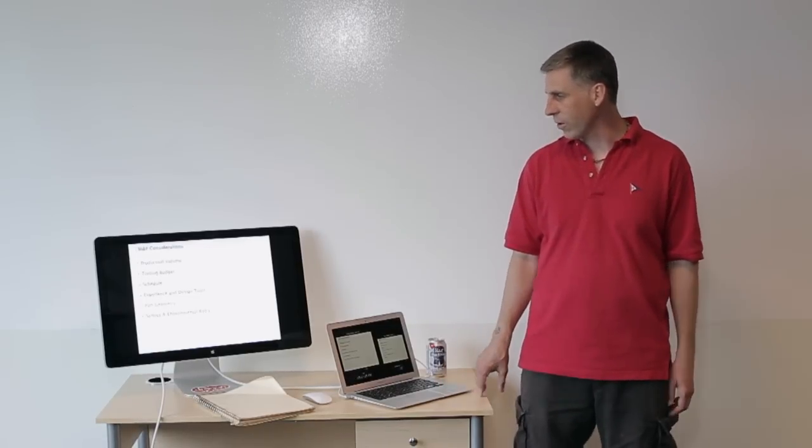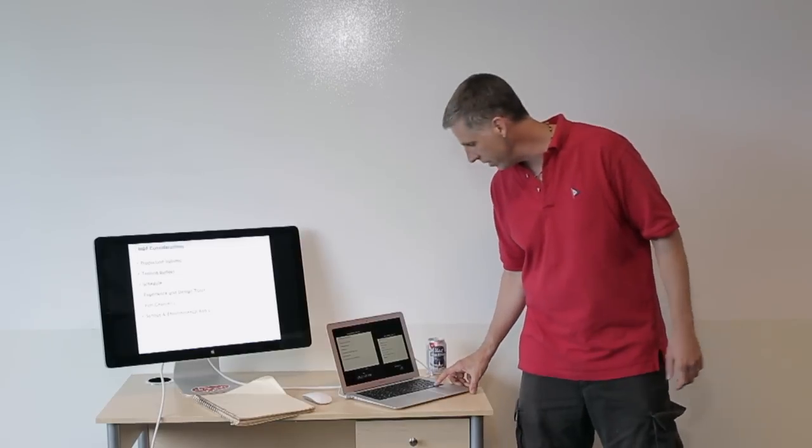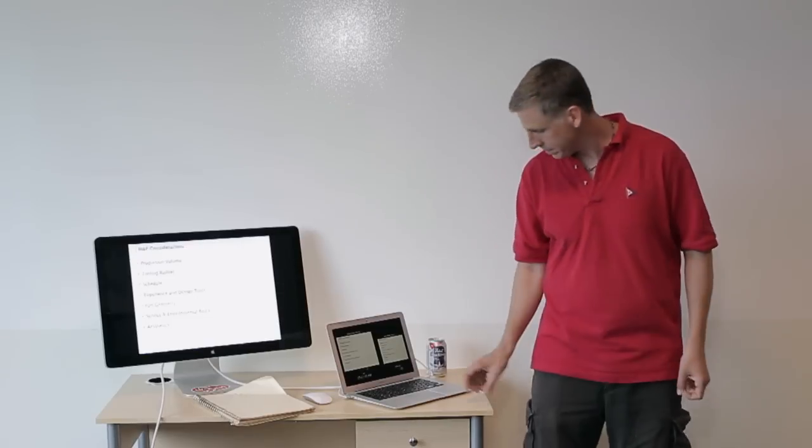Any sort of service or environmental requirements. So does it have to work in an acid bath? Does it have to work underwater? Does it have to be user replaceable? Does it have to be safe for a user? Those are all things you want to bake into your decision. And the aesthetics. Is it a cosmetic surface that people are going to interact with, or is it buried inside the device? And the accuracy. Is it a precision piece of equipment that has to hold very tight tolerances, or is it something that's a little bit more forgiving?